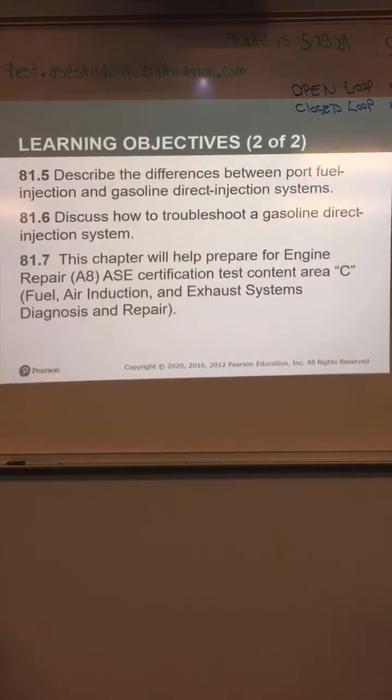I'm gonna go through some of the differences, how to troubleshoot the GDS system. One of the other disadvantages that we didn't get to, but we will, is carbon buildup on the intake valves. Port fuel injection squirts fuel right directly on the intake valve, right? So it kind of helps clean it. When the fuel is injected into the combustion chamber, the intake valve no longer gets cleaned from the fuel injected.